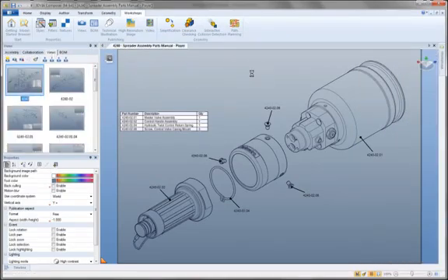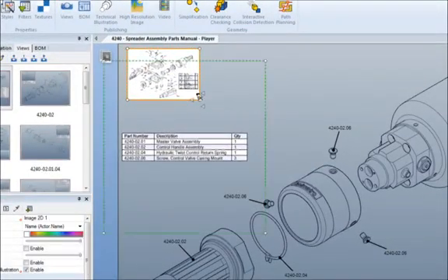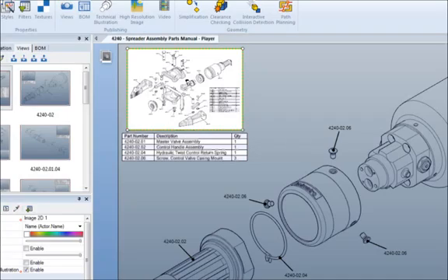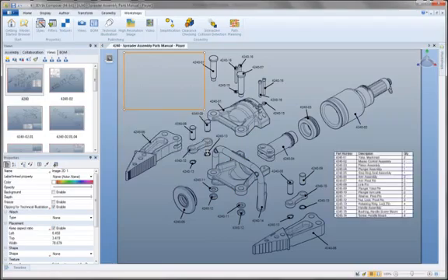In the case of an online part manual, we utilize 3D via Composer's intelligence to include an interactive bill of materials. We can hyperlink components and create dynamic panels. For example, to return a user to the top-level assembly view, we can utilize a small image as a virtual back button. Navigation is aided by rich graphical content.